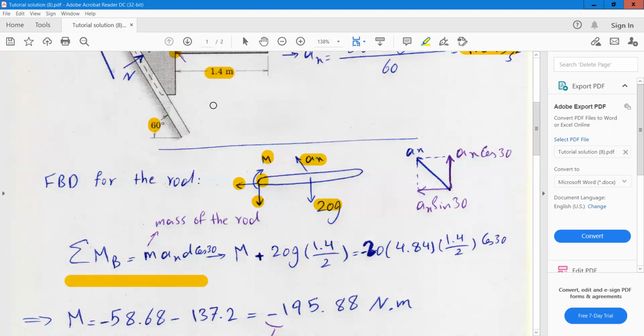We will have the moment equation about B equal to 0, because this is a translational motion and there is no angular acceleration. But in the right hand side, because you are writing the moment equation about another point other than the mass center, as I told you, we will have m a d. So this term is an additional term that we will have in the right hand side.